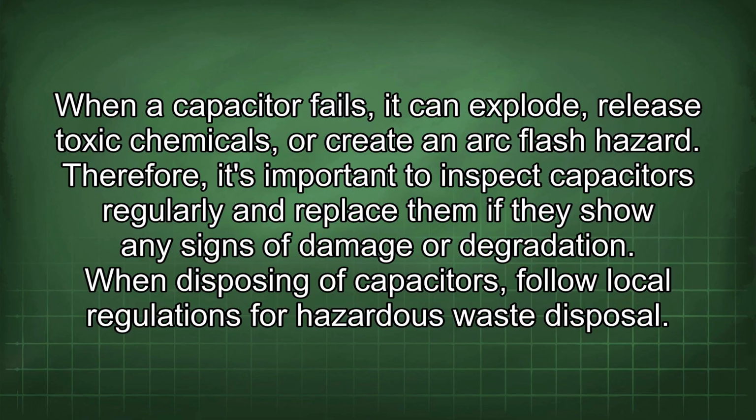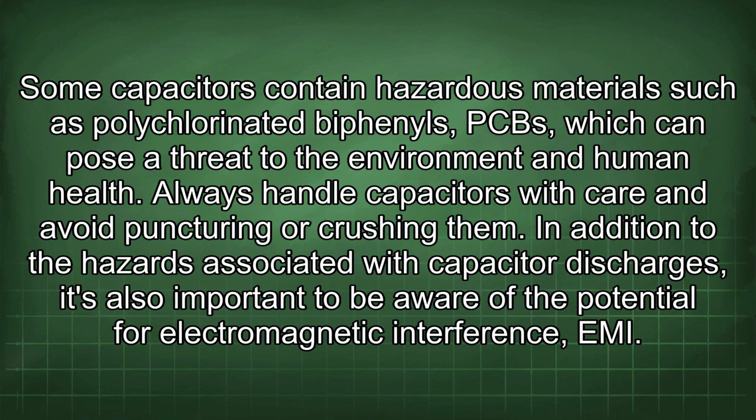When disposing of capacitors, follow local regulations for hazardous waste disposal. Some capacitors contain hazardous materials such as polychlorinated biphenyls (PCBs), which can pose a threat to the environment and human health. Always handle capacitors with care and avoid puncturing or crushing them.